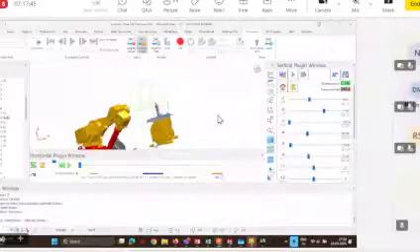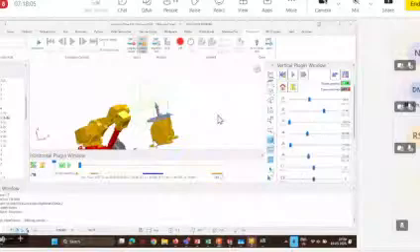All right, so it's just showing a collision because the gap is too low. If we increase the Z height over here, then you can see how it's going to work. This is the case: we have the substrate at the bottom, so anyhow we need Z height to work properly. Now if you run the simulation, again it's still showing the collision. So we just need to increase it more, and then it will be perfectly fine.